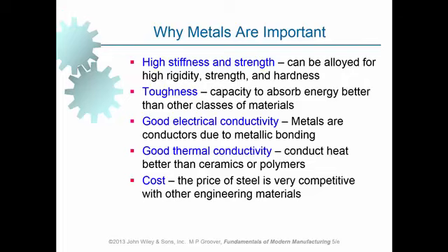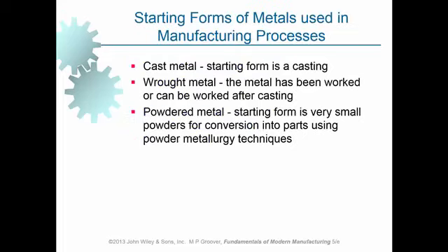If we go for polymers, how about polymers? Can we make use of polymers in order to make the body of the car? We may, but it will not be as desirable as metallic material. It will not be as strong as metallic material, of course. And when it comes to, say, resistance to heat, in hot days of summer, maybe the color and also the shape will change. However, we can make use of composite materials in order to produce the body of the car, and in some certain types of cars, the body of the car is made of composite material. Okay, let's move on.